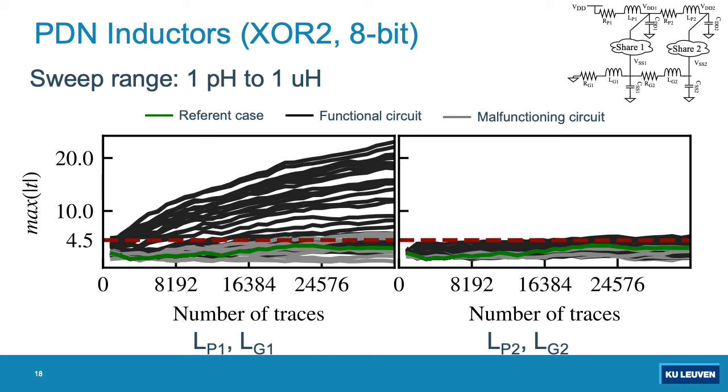Therefore, there is some sort of a nonlinear mixing of the supply currents of the share 1 and share 2 over these inductors, causing the voltage drop that in a way couples the two shares. Now, in practice, existence of significant parasitic inductors in the logic core would very quickly lead to an oscillatory behavior, quickly obliterating the circuit functionality.